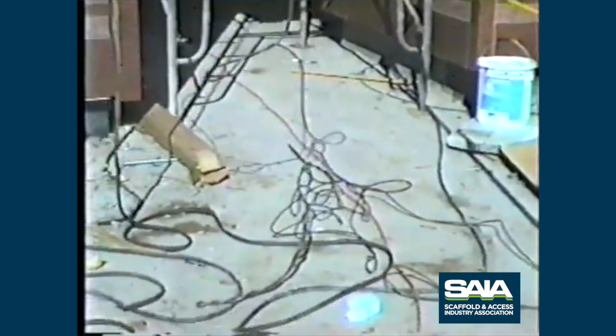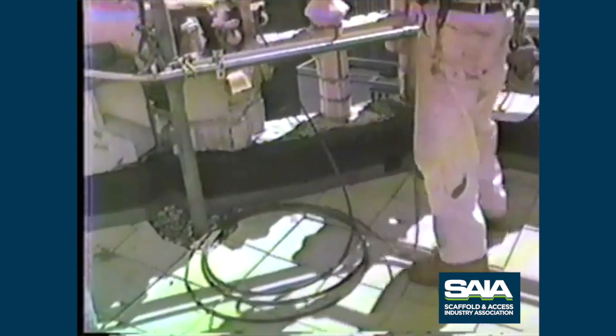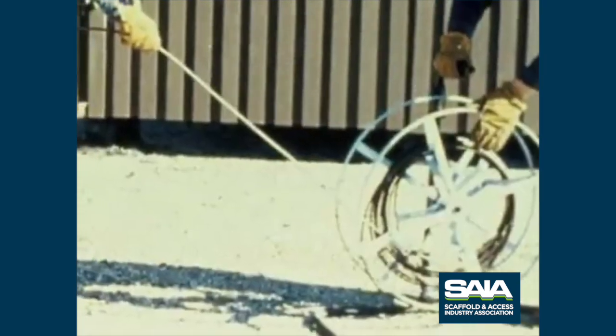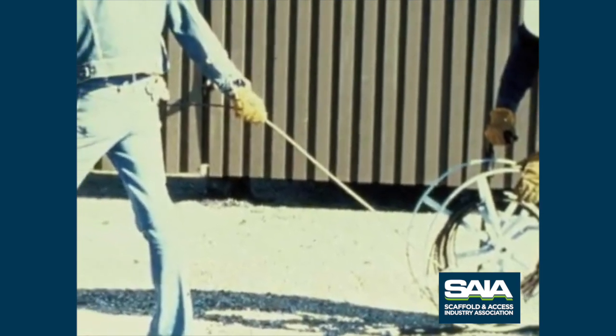Avoid kinking rope when unwinding it. Wear gloves and handle properly. Do not lay a coil of wire rope on its side to unwind. Use a mechanical assist when lowering from tall structures to maintain control. Use caution in windy conditions.